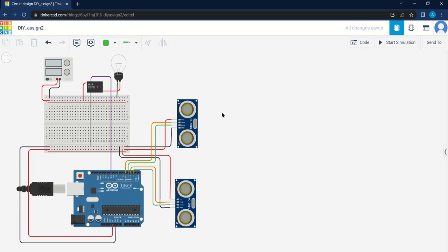That is, when a person enters an empty room, the room's lighting will turn on and will remain so until there is at least one person in the room, and when everyone exits, the room's lighting will automatically turn off. Hence, this can help by automating the room's lighting system, as well as conserve energy by turning off the lights in empty rooms. For this, I mainly used an Arduino Uno, a 4-pin ultrasonic distance sensor, and a single pole double throw relay.